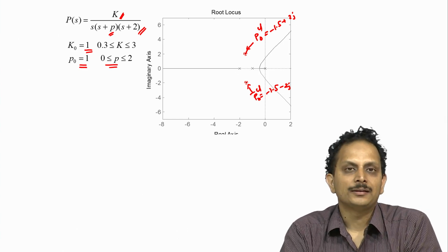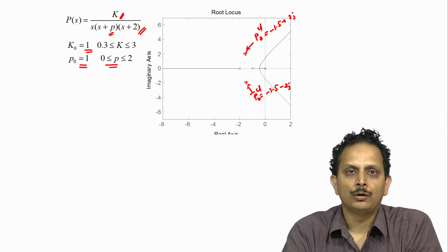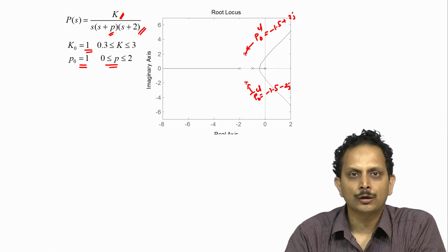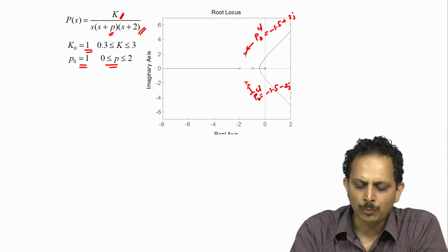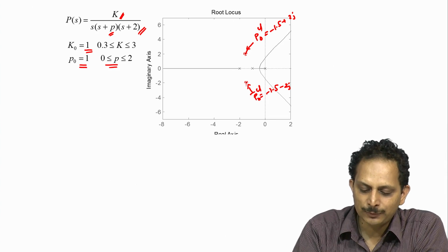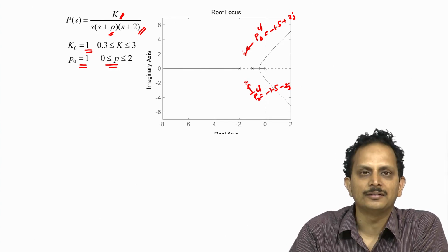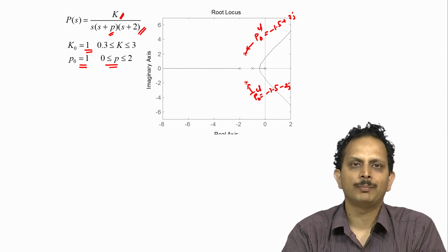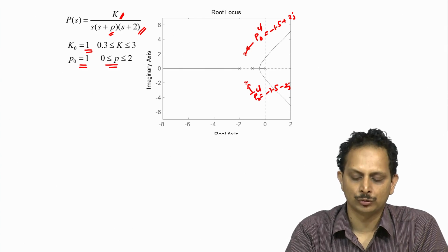However, when the pole location varied or the gain changed, we expected that the closed loop pole should wander by a small amount about its nominal position, and this has been indicated in this graph by this tiny dotted circle that I have drawn here as the area within which we were okay with permitting the variation in the closed loop pole.